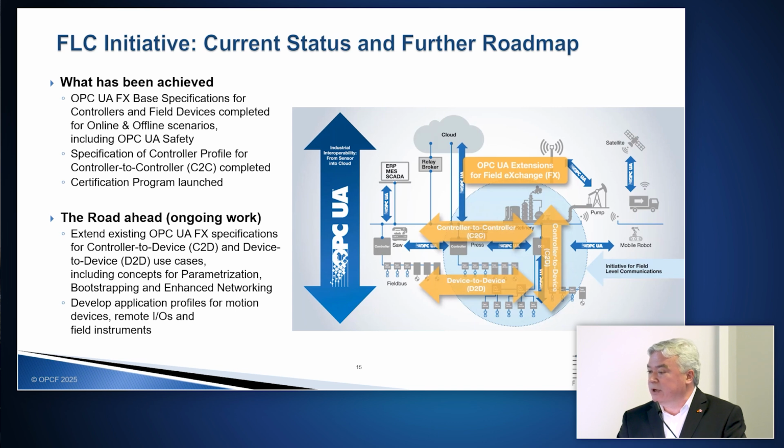become the agreement, or got the agreement, with all the key automation suppliers to agree on exactly one controller profile. So this is, let's say, the construction description, how to build an OPC UA FX compatible controller. And there is exactly one. This is why I said it's a generic approach. It can be any kind of controller, PLC, a DCS system, a robot controller, whatever. And this is also completed, agreed.